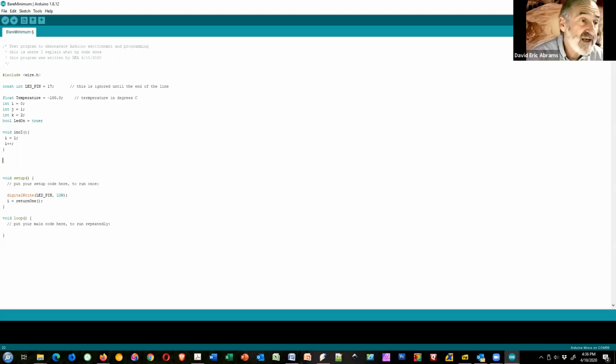The other reason we can move things into functions is, what if our hardware changes? What if the way we check that the door is open changes? Well, that's not really important. If we want to check if the door opens, we want to turn on the lights, we want to do stuff, we don't care how we check if the door opens. We just want to know if it's open or closed. By moving it into a function, we isolate the complexity of checking if the door's open from the actual thing we want, which is whether the door is open or not. So use functions to isolate hardware in particular, which might change, but also just to make your code more readable.